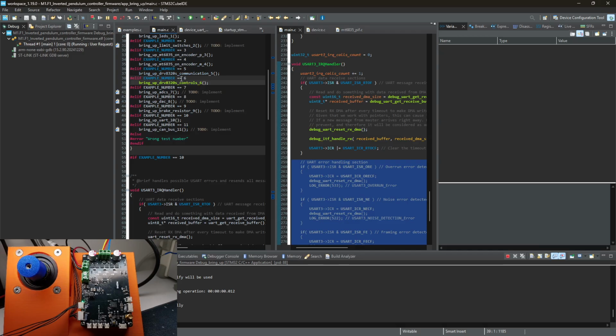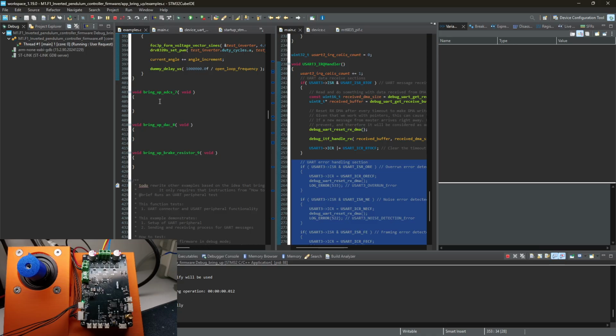Nice. So ADCs. ADCs will be tough, because ADCs, at least for this project, are... Like, there is an interesting problem to have when you implement FOC on a microcontroller. And the problem is that you almost always require at least 3 ADCs, like separate ones. And by a separate ADC, I mean a separate peripheral. For example, in STM32, the one I use has only 2 ADCs, ADC 1 and 2. And this is not enough. And why is it not enough?